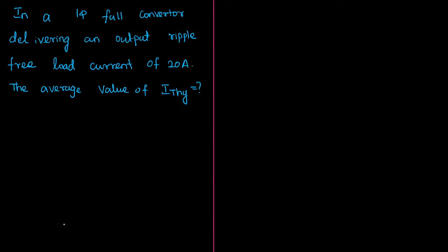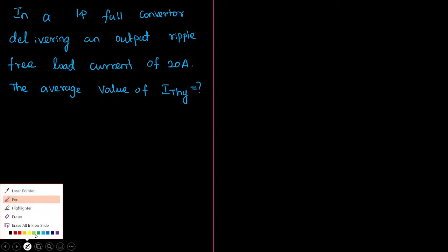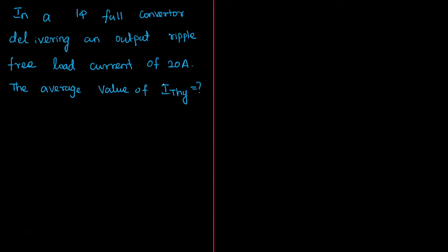See, this last question we have already discussed. There is nothing big. I have drawn it from everything I did already. Kanaga Savita, good. Same. What is the relation? The average value of the thyristor current we got is simply equal to the output current I naught upon 2. And we also figured out the RMS value of the thyristor current, which gave the relation as I naught upon square root of 2.